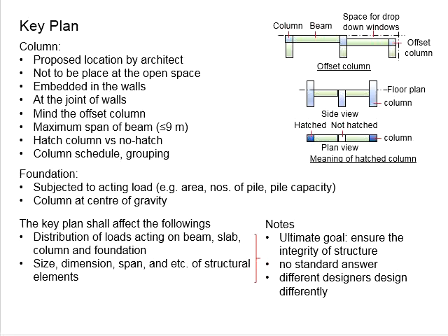Make sure all the columns within the group will not fail, and there will be about 10 groupings of the columns to cover a total of 100 units of columns in the building structures. Then this will be quite easy for the contractor to monitor as well as to construct on the construction site.